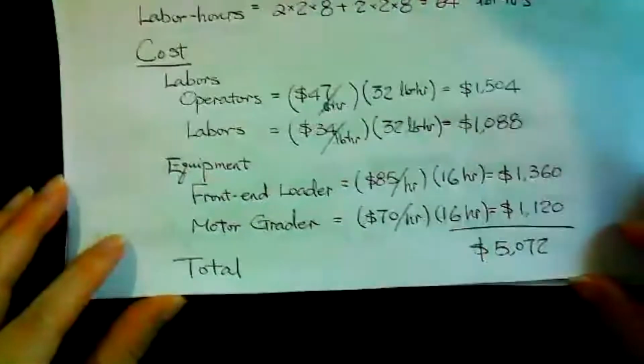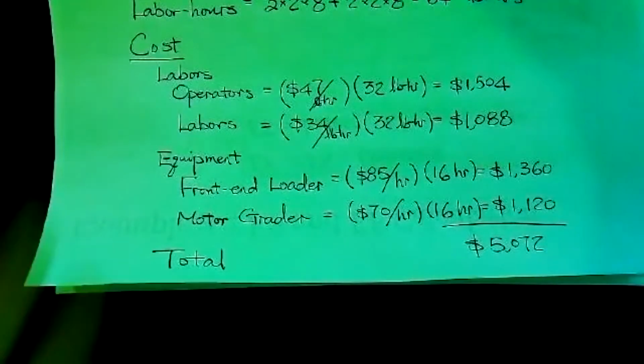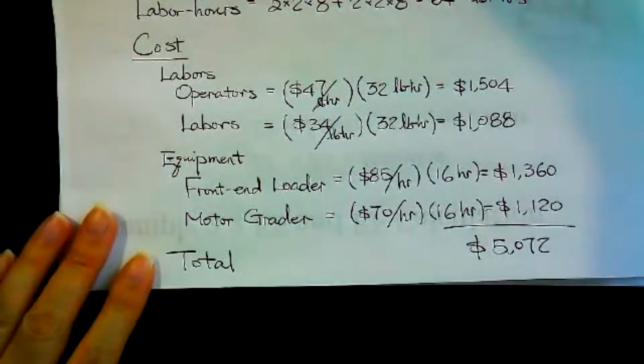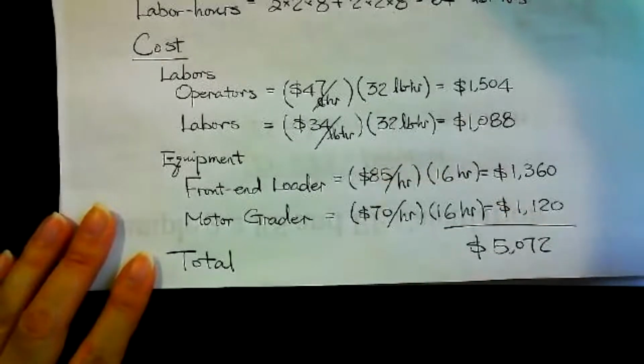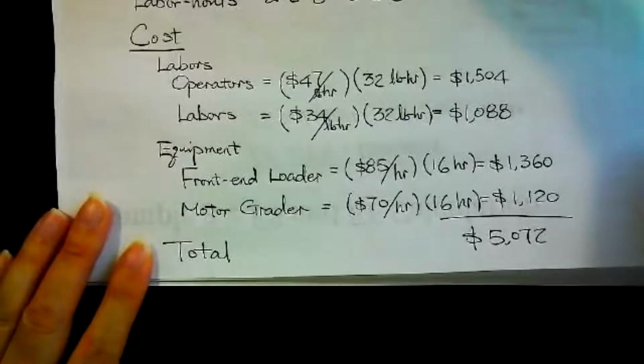That's how Primavera calculates each type of labor and each type of equipment. And given the period of time, it gets a summation for you. So you can break out each type of labor separately, and for any window of period. So Primavera does the same calculation, the summation for you.